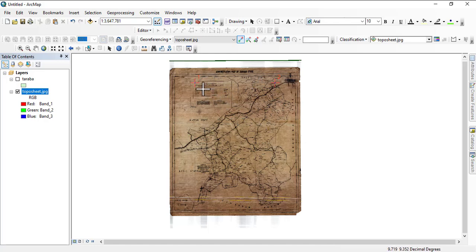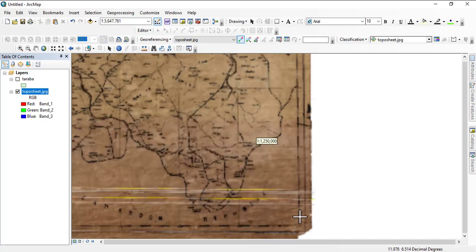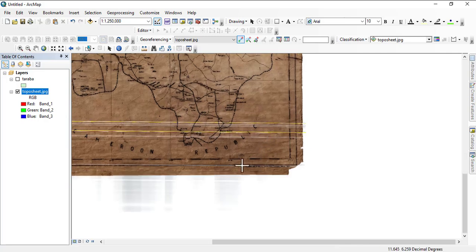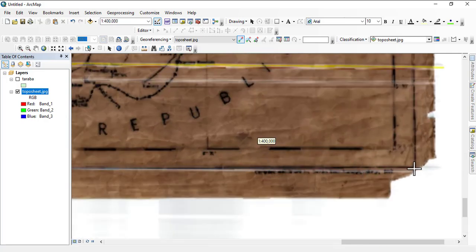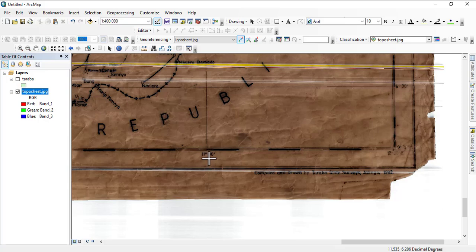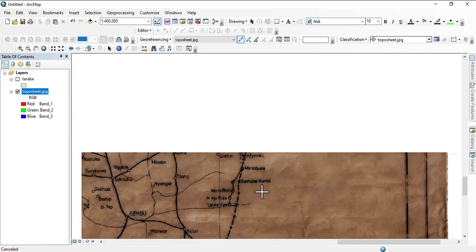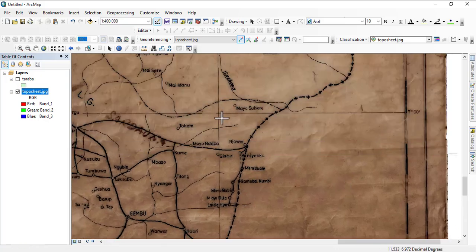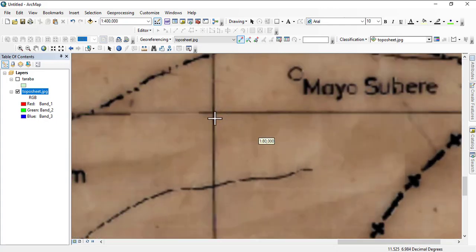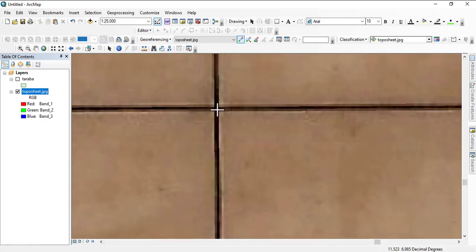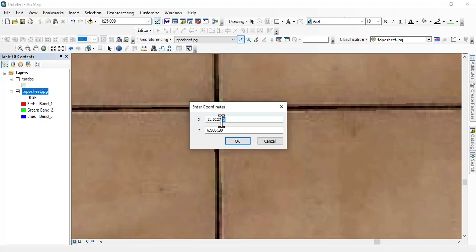So we have 2 more points to go, and we're going in a clockwise direction. So we go like this. Okay, so now we're going to zoom it down here. So when we zoom to this place, we see that we have 11.30. So we either come up to this 7.00 or we use the down one, but let's use this 7.00. So we see an intersection, the second, so click, then we right click and we come to this. So our easting is already giving us 11.5.